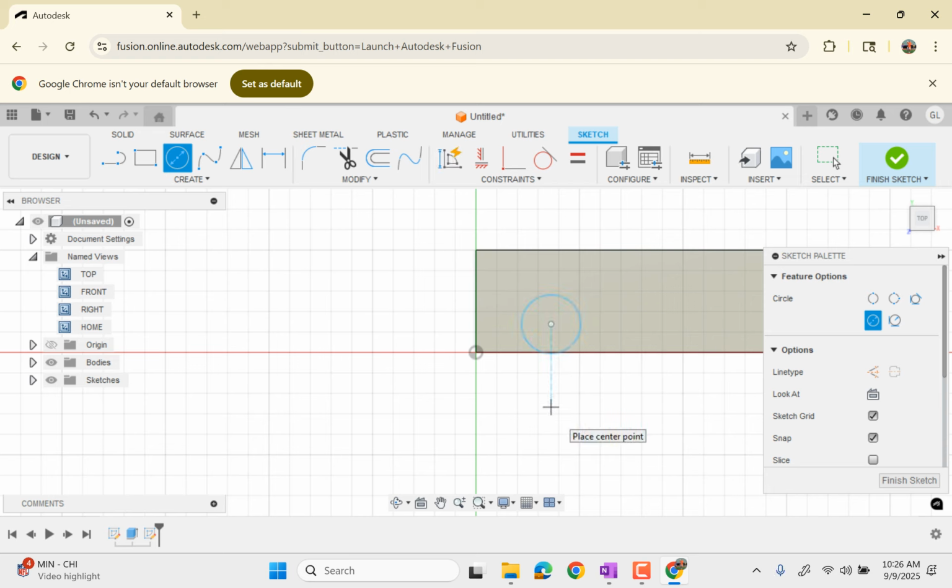I have gotten in the habit of locating things when I draw them at sort of odd locations so that it's not making assumptions about where I put stuff. And then I can use dimensions to put it exactly where I want it. Sometimes if it makes assumptions about constraints of where stuff goes and it's not what you want, it can be sort of a hassle to undo those constraints.